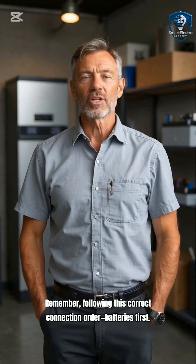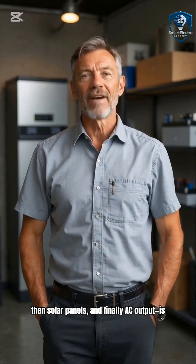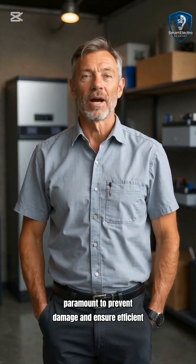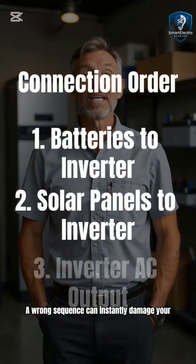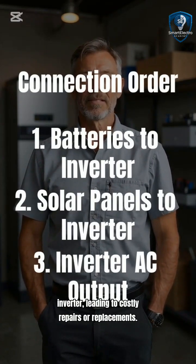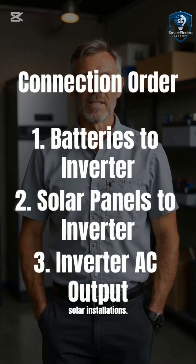Remember, following this correct connection order, batteries first, then solar panels, and finally AC output, is paramount to prevent damage and ensure efficient operation. A wrong sequence can instantly damage your inverter, leading to costly repairs or replacements. Always prioritize safety and precision in your solar installations.